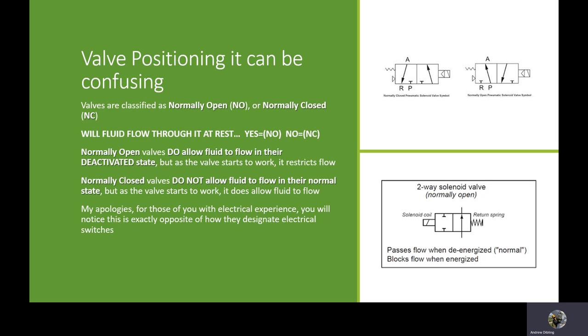If you're familiar with electrical technology, my apologies. Normally closed in electrical schematics is the opposite of a fluid system. It's just something you're going to have to get your head around. It takes a little while. What I find helps is following the arrows.